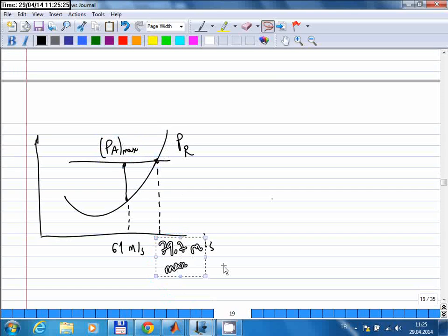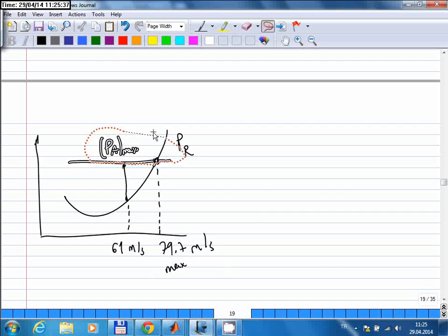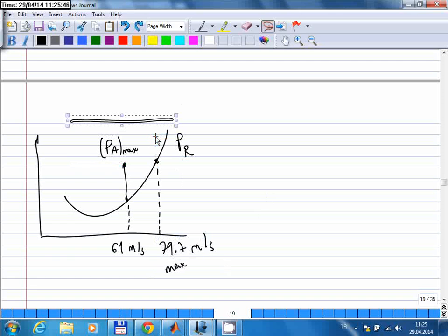Because to be able to climb, you need to have more power than what is required by the flight. And since your engine is already running at its full power, you cannot increase this, right? You cannot do that and get excess power because you don't have more power you can get out of your engine. So again, an aircraft flying at its maximum speed cannot perform a steady climb at all.